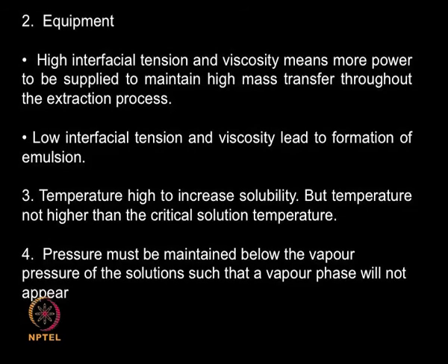Higher the viscosity, higher will be the power requirement. If I have low interfacial tension, it will also lead to formation of emulsion. So, I need to be very careful that if I agitate too much in a low interfacial tension system, I will be forming small emulsion droplets, and that means I am losing my product in those emulsions, and breaking the emulsions is not so feasible.